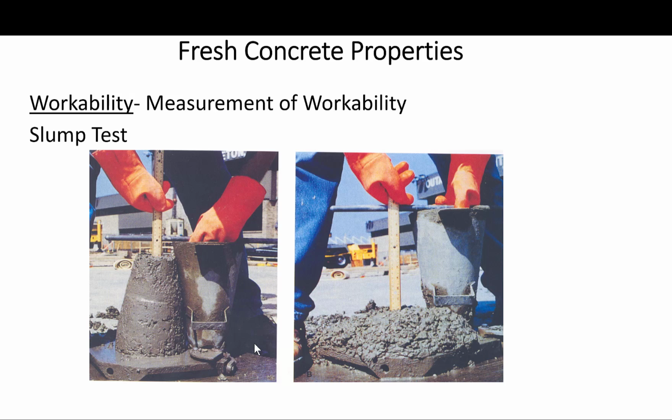A large number of workability tests have been proposed over the years. Almost all of them are completely empirical. Only a few of these have been incorporated into standards. The rest have received very limited use. So we have to keep in mind that none of the available standardized tests measures workability in terms of fundamental properties of fresh concrete. Okay, none.